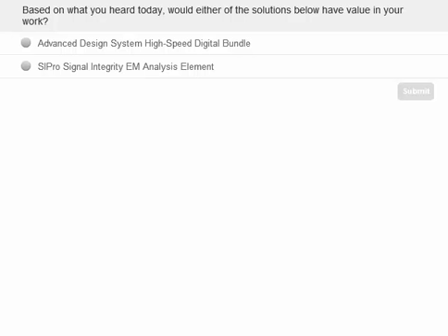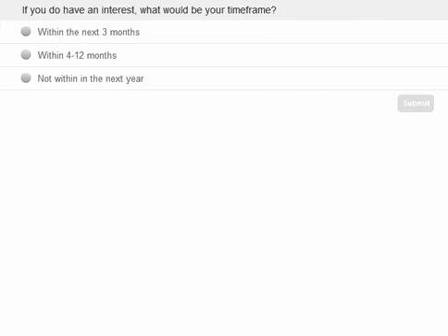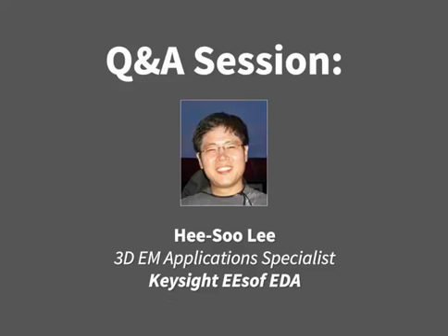First question: can you discuss ground bounce? That's a good question. As I mentioned in one of the slides, ground bounce is the same behavior, but coming from the ground plane instead of the PDN. In order to do ground bounce analysis, the same concept is applied.